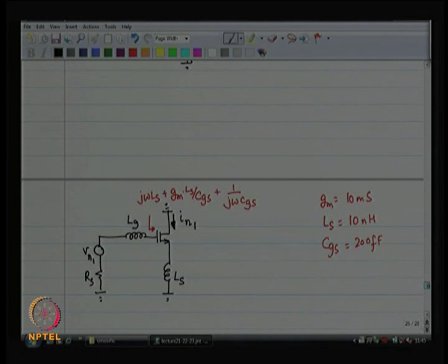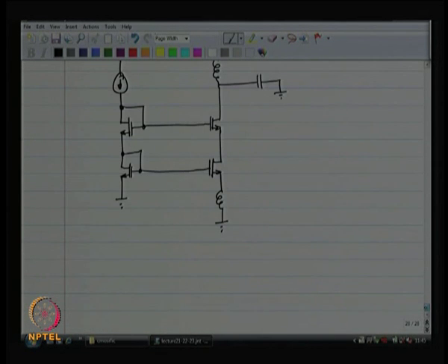And I also want to place an inductor and connect it to my signal source. But if I connect it directly to the signal source like I have done over here, then the signal source's DC voltage, which is 0 volts, is going to propagate, and as a result the gate of the MOSFET will be biased at 0 volts, which is not something that you want. So, you put a blocking capacitor over here.